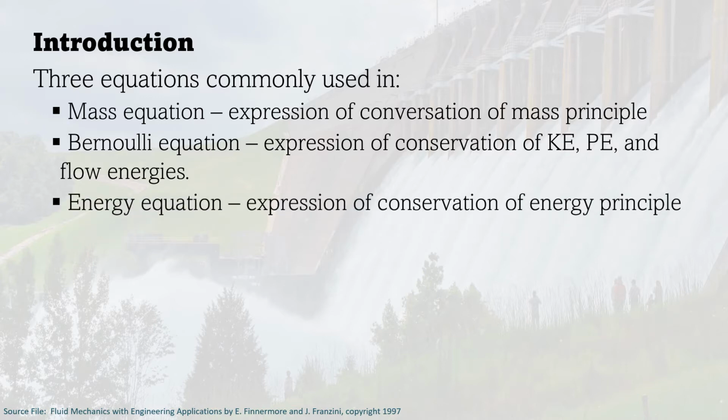The final equation is the energy equation, which is a statement of the conservation of energy principle. In fluid mechanics, it is found convenient to separate mechanical energy from thermal energy and consider the conversion of mechanical energy to thermal energy as a result of frictional effects as mechanical energy loss. Then the energy equation becomes the mechanical energy balance.